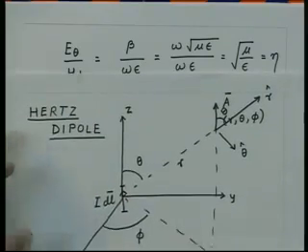So, this wave is a spherical wave and it has a transverse nature, that the electric and magnetic field both are transverse to the direction of the wave propagation. So, we have got here what is called a transverse spherical electromagnetic wave, and it has all properties of a transverse electromagnetic wave, like the ratio of the electric and magnetic field should be decided by the medium properties, which is the intrinsic impedance of the medium, and the electric field, the magnetic field, and the direction of the wave propagation should be perpendicular to each other.